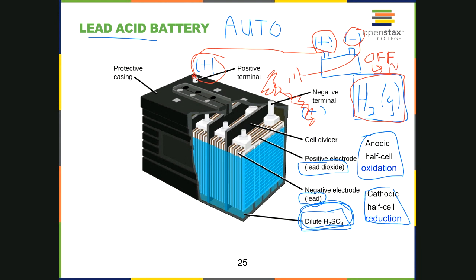At that point is when you can have the donor battery person turn it on. Anyway, they start their car, let it run a while, leave this hooked up, and then when you're done, they ought to shut their car down. You ought to disconnect the cables and try to start your car, and not try to start it with the cable still connected. Okay, that's the safest approach.